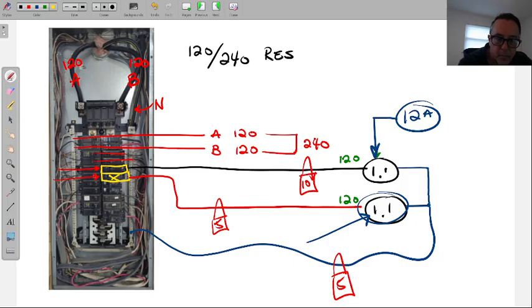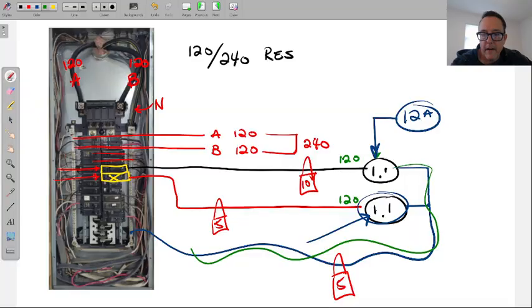Well, I'm going to turn this breaker off. But here's what happens to those 12 amps. Where are those 12 amps going? They're heading back, but they're also here at this outlet. So if you leave the other breaker on with something still plugged into it, generating load current, this is the one that, when you were talking all that safety stuff, kills us.